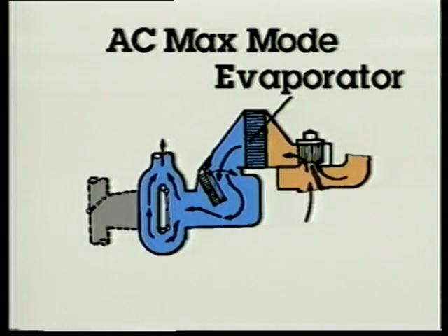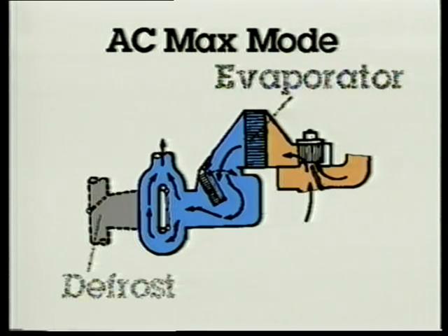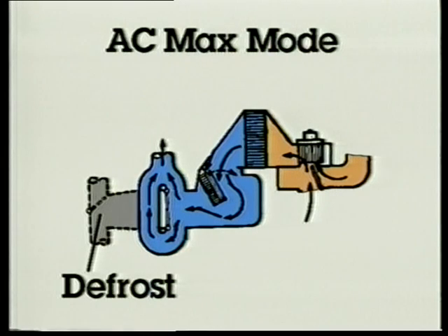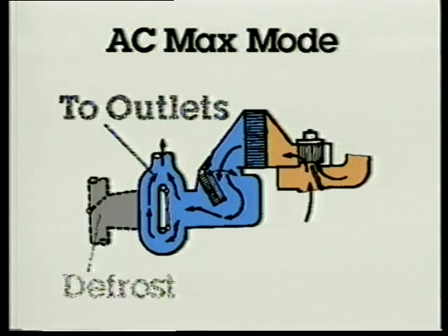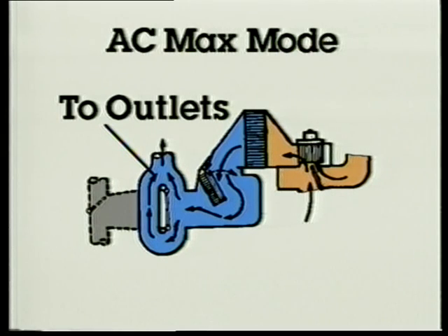A service manual will give charts like this one for each control head position. It will give part locations, air door positions, and arrows showing airflow for each lever position. This will help you find the source of a problem if air is not directed out of the vents normally. Again, refer to your service manual because it will give charts for each position and for the exact type of heating and air conditioning system.